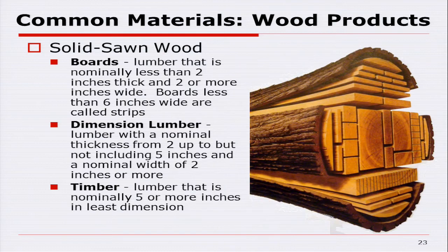We basically have three categories of lumber, and if you're an engineer, and especially in wood design, you become very familiar with these sizes. The rest of the public probably misuses all these terms as far as we're concerned as structural engineers. Boards are members that are nominally less than 2 inches thick. So a 2x4 is not a board. And by the way, a 2x4 is actually less than 2 inches. I say nominally, in name only.